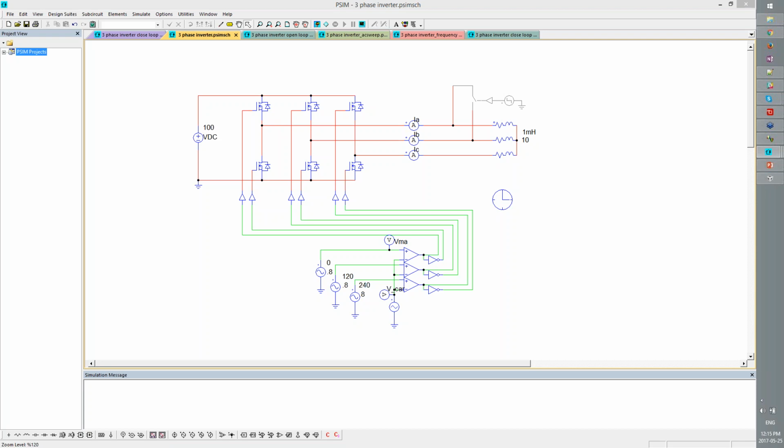I always thought RCP is connecting a real-time simulation. There's a question that's come in about the ECU and the real plant. So we're going to be generating the code and running the code in real time, and then verifying the operation with a real-time hardware-in-the-loop simulation, which is what the HIL block is doing. So it's a full process that we're coming through. So yes, we're doing a real-time verification of the control code on the DSP against a hardware-in-the-loop simulation,